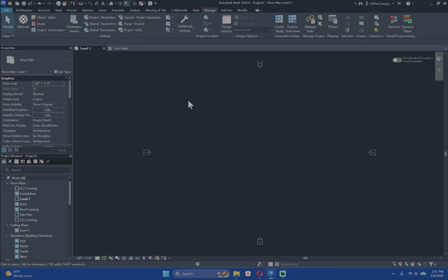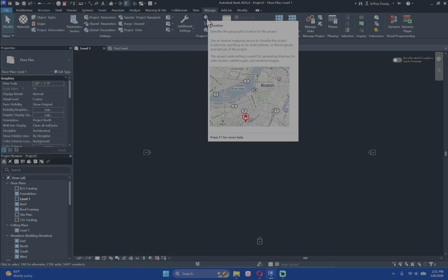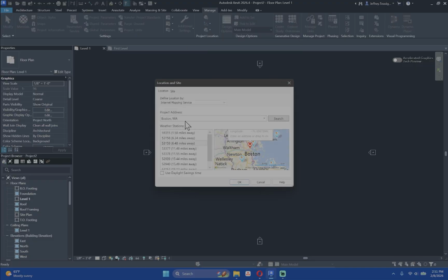So we've got our project information input. If you do know where your building is, and this is going to be important for this class, you will need to go up to your locations area, which is a little planet with a waypoint symbol, kind of like you'd see in a type of maps application. If you select that, you can put in exact addresses.